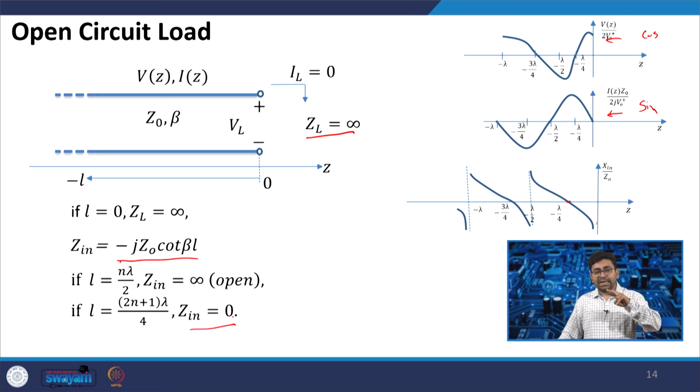That is also the beauty of the transmission line, you can convert open to short and short to open just by changing the length of the line. And if you consider the lambda by 2 line, you will get the same behavior. So, if it is infinity, you will see the infinite impedance, that is an open circuit. So, these are the two special cases of the transmission line.